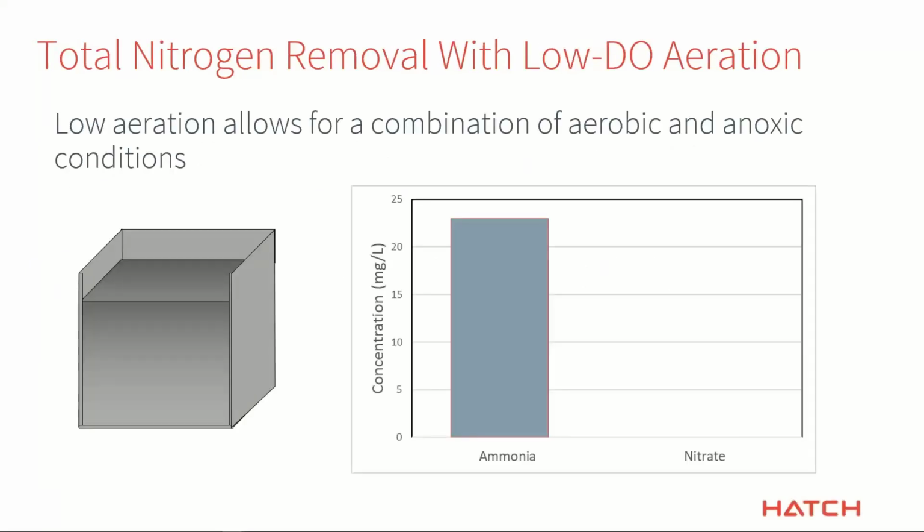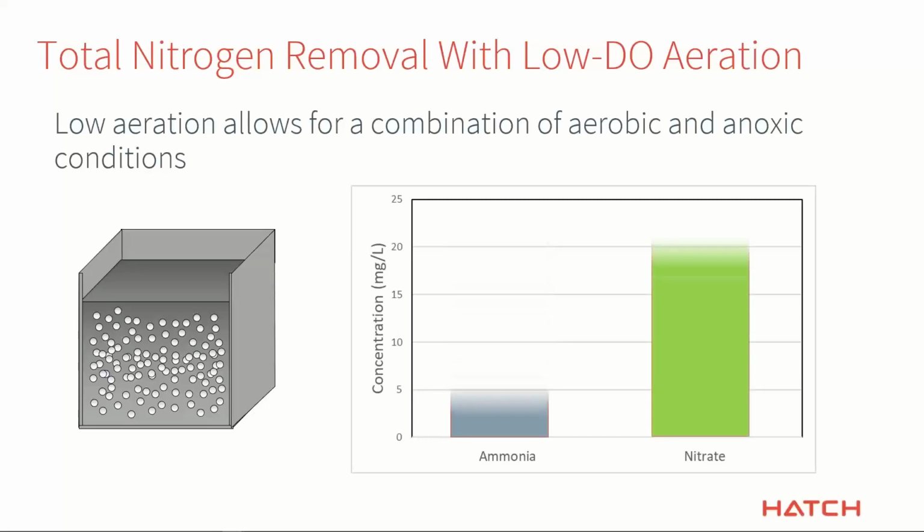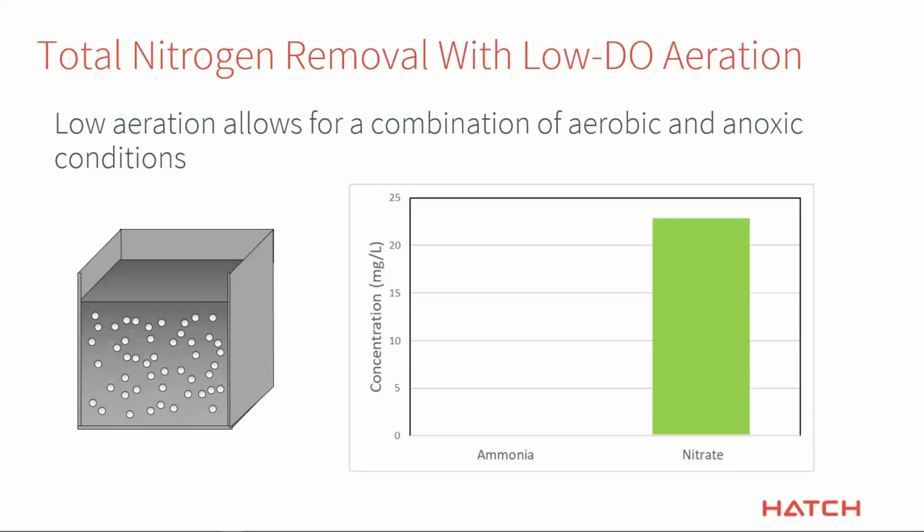So what that looks like in terms of process is, instead of saying I'm going to completely get rid of all the ammonia, when I go to the anoxic phase, I don't go all the way off. I leave some aeration happening there. You can find a medium ground where you're not going to do as much nitrification and ammonia removal as you would otherwise, but you can do it enough that it gets into nitrate and then denitrify it all in one shot.